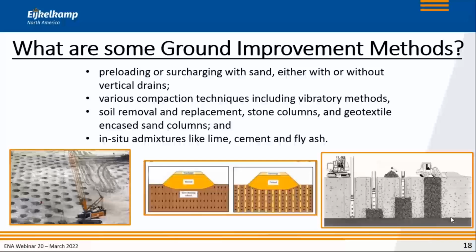as you see in the bottom center. And then you can either let the groundwater seep out, or you can make it a little bit easier by applying vertical drains, whether wick drains or sand trenches, whatever you want to do, as you see indicated by the black arrows. The black arrows in the left-hand side, obviously the water has to escape through the top. And then on the right-hand side, the groundwater penetrates horizontally to those wick drains or those vertical drains, and then through there comes to the surface.